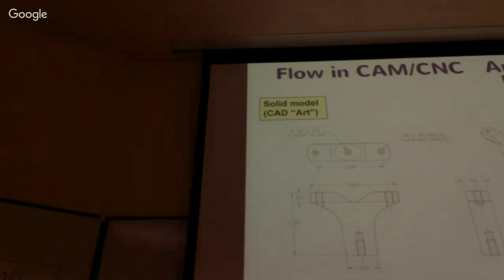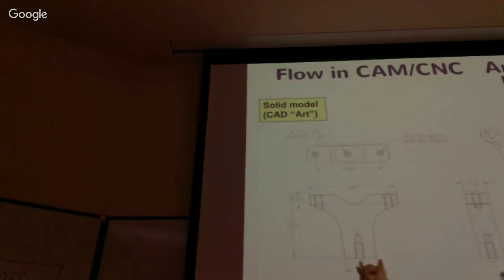It looks like you turn down the end there. So what you're doing now is you're trying to determine what machining processes you're going to use to make the part, right? So actually, we don't turn it because it's not symmetrical. It's narrower in this orientation than it is in this orientation.